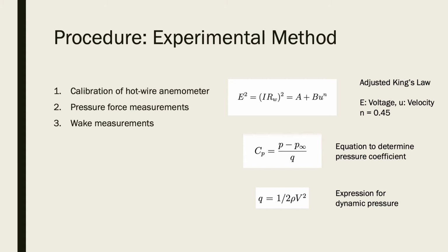To measure the pressure force, LabVIEW is used to output the difference between the static pressure upstream and the static pressure measured on the surface of the airfoil at the static pressure tap locations. This pressure difference is used in the equation to find the pressure coefficient, as shown. Q is the dynamic pressure and is constant through the experiment.